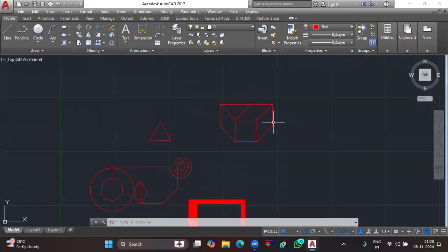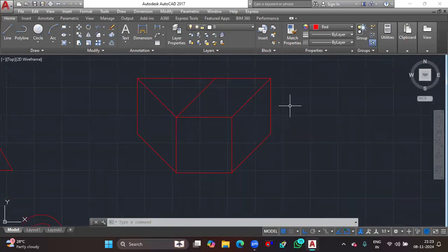The first one is 2p circle. 2p circle means it needs 2 points. It is meant for scenarios where you don't know the diameter, but you know some kind of reference lines. In that instance, you can use this 2p circle.